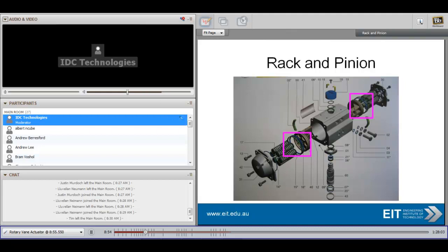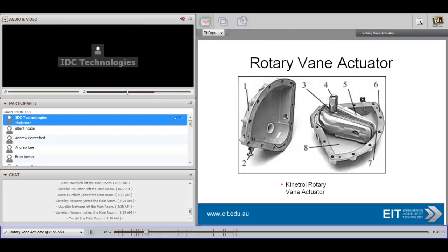Now, these aren't the only pneumatic actuators you can get. You can get something such as a rotary vane actuator, which is a good alternative to piston actuators, especially where high loads are going to be encountered. There are no links and gears. It is bulky and heavy. Maintenance problems do occur probably more frequently than you would like to have them, but it is something that one can actually have a look at.